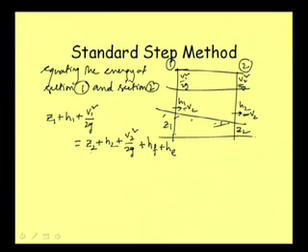Well, that is why this particular method, the standard step method, has another advantage of being used for a non-prismatic channel also, because this sort of eddy loss is prominent or important in the case of a non-prismatic channel.